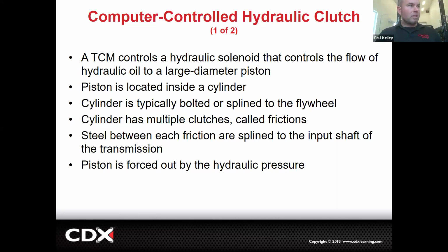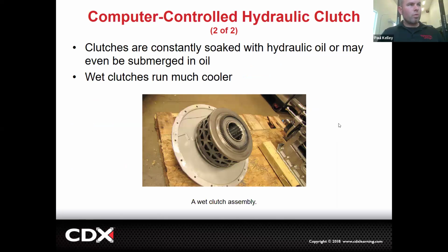Okay, so this is a hydraulic controlled wet clutch. So there's going to be 2 clutches in here, and each one is going to go to an even shaft or the odd shaft. Now the shafts aren't like this. There's a shaft in the center and a hollow shaft on the outside. So it's either going to grab the middle or grab the outside.